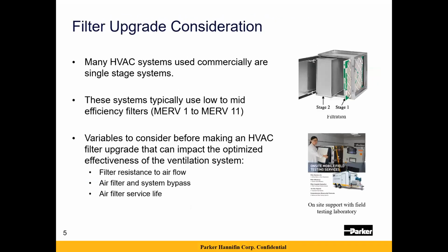So what you're going to have with the current pandemic and the current situation is that you're typically going to have people looking for MERV 13 and higher filters. This is the current guidance from both CDC and ASHRAE. In some systems, that makes it possibly a little bit difficult to make a filter conversion. There's a lot of multi-stage systems out there and a lot of single-stage systems out there. Multi-stage being shown up in the upper right-hand corner. You could have 1-stage and 2-stage filters. In those kind of applications, it's probably fairly easy to switch over and switch your second stage to a higher efficiency filter. There are a lot of options available for that.